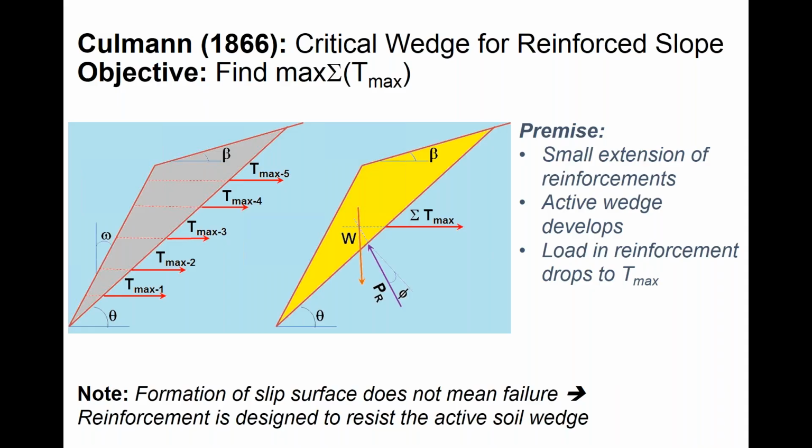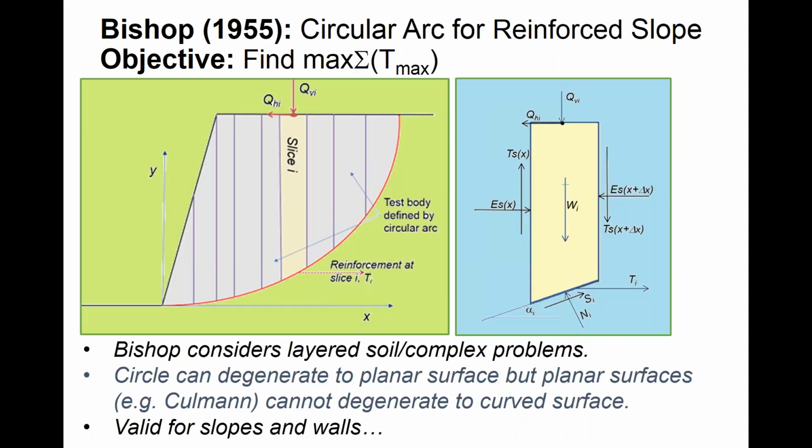So just as before, note that formation of the slip surface doesn't mean failure. It just gives a condition where the reinforcement is designed to resist that active soil wedge. Now, let's get a little bit more complicated, but it's the approach we'll apply today. And just so you know what it is, we got to talk about it for a second.